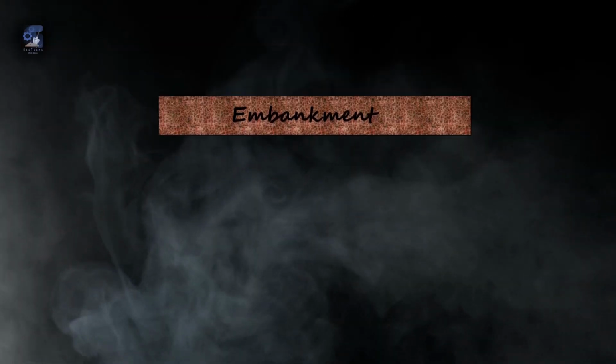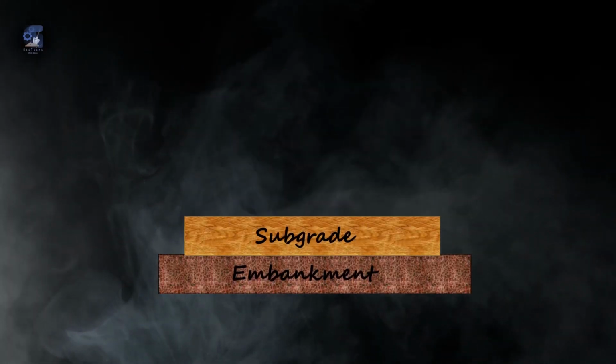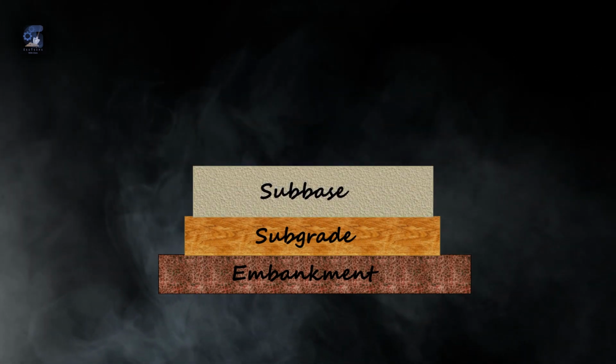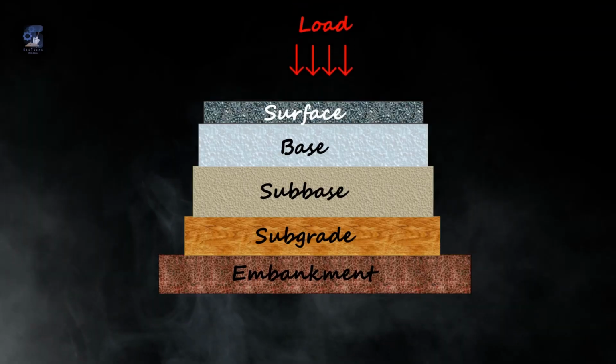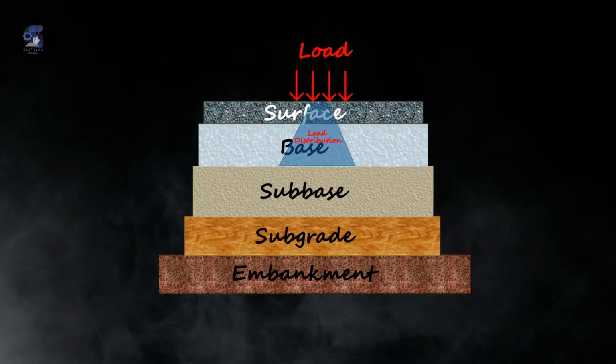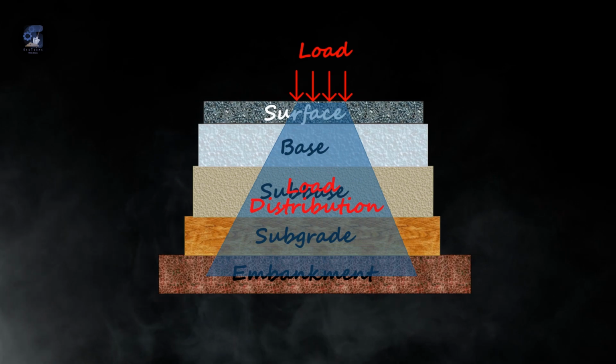Road pavement structures typically comprise an embankment, compacted subgrade, a subbase, a base course, and a surface course. A well-designed and properly constructed pavement structure should be well balanced in terms of how the traffic load is distributed along its layer depth and its resistance to the environmental factors.